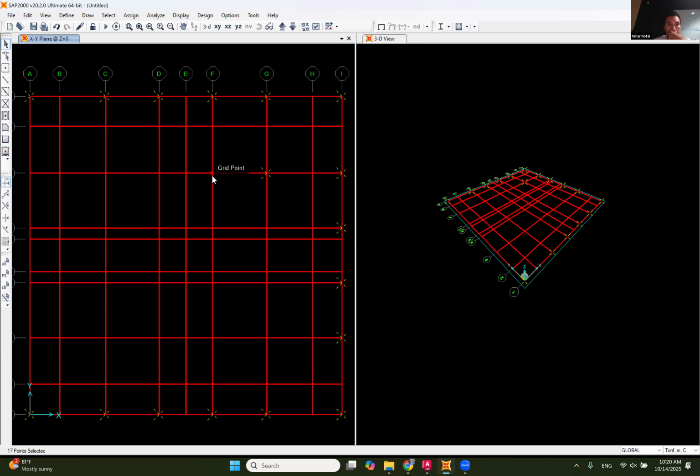All right, I had one here. If I drag and draw a rectangle to select them, it also selects the slab area. Does that matter? Yeah, actually, it's the joint in the slab. What we did here, like this division, this is a slab, and this is a slab. So basically, you generate a specific point on the slab that can drop the load at the column.